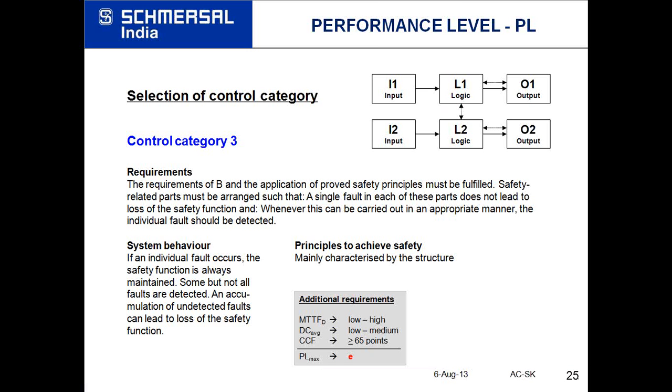The push button contacts or the push button itself acts as an input, and then the logic part which takes the signal from the push button can be a PLC, a safety relay, or a microprocessor based logic controller. The output is nothing but the motor controlling devices like contactors, drives of the motors, or MPCBs or MCCBs. These you can consider as output.